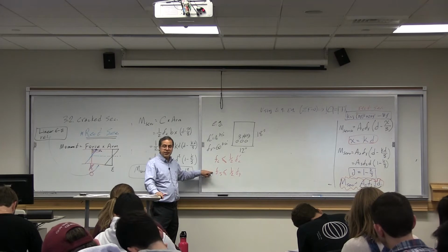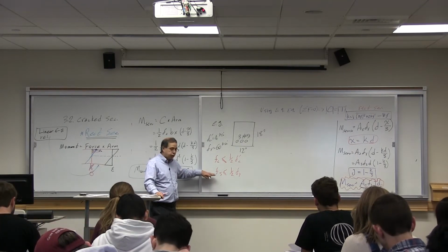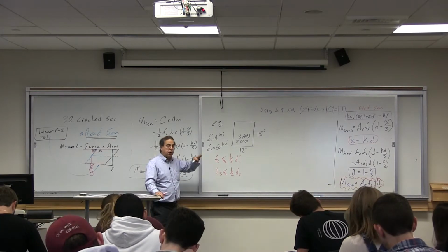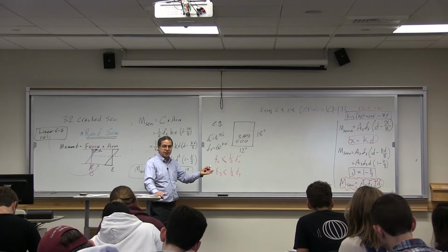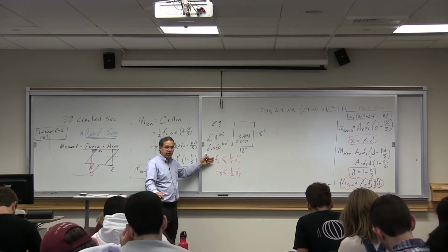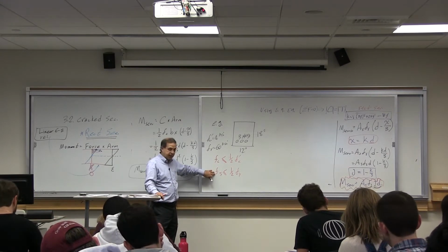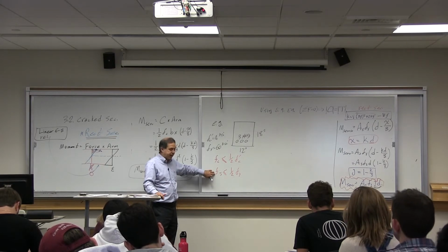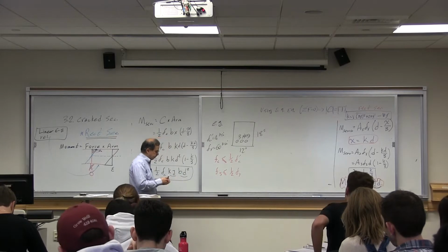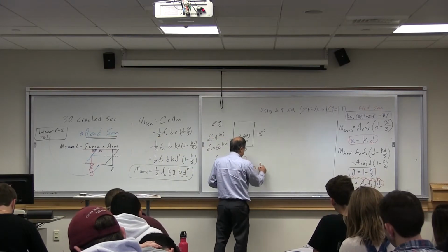What do we control with this limit? Crack size. So this controls concrete in tension. We are putting a limit on the steel bar to control the crack size. So this would control crack size, and this would take care of concrete in compression. This also limits the rebars in the linear range. If it's less than Fy or even Fy, it would be linear. So if we have these two, the question is,